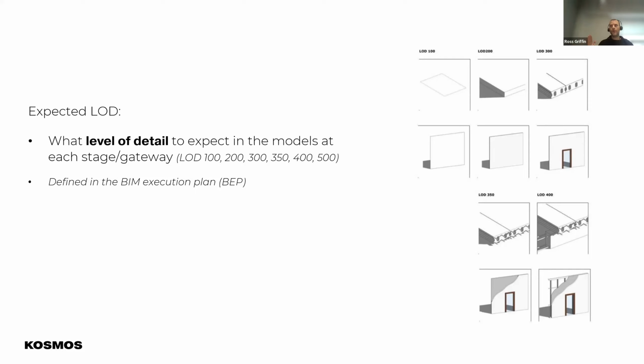And again, we move through the level of detail into 300. Suddenly, you can see now it's hollow core slabs, and likewise into 350, the inclusion of reinforcement or joint information, etc. LOD 400? We'd sometimes see it on projects as the for construction model. But that being said, 350 is generally what we would deal with to date. And the 500, as I say, I haven't seen on a project yet, but that will be the future. So it's good to at least understand these.